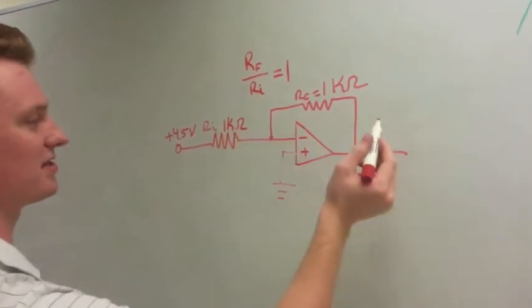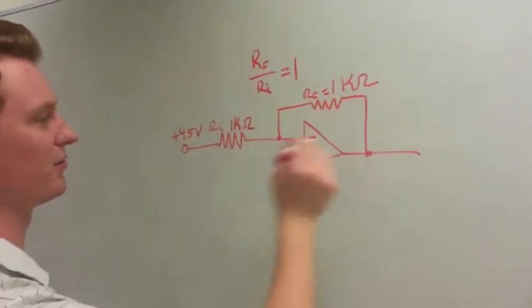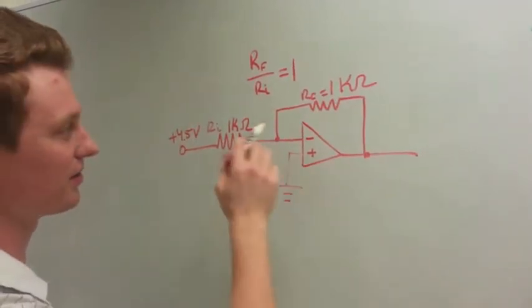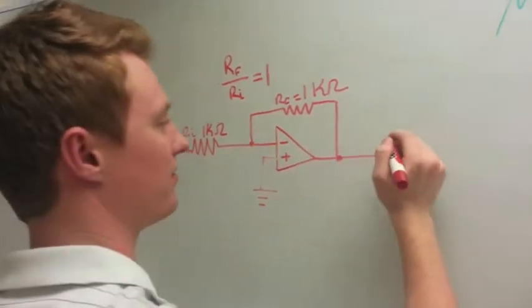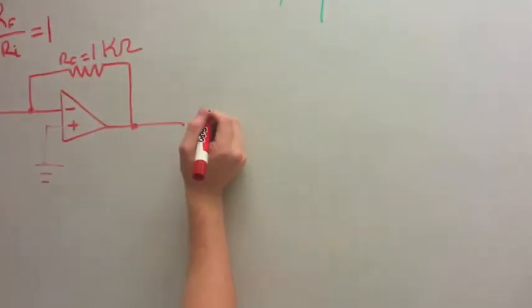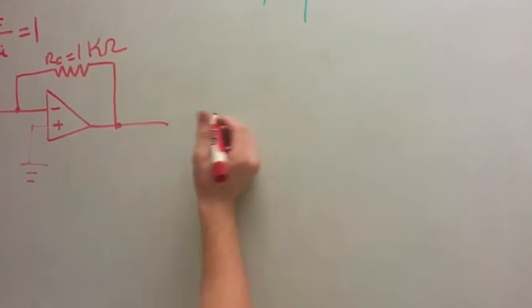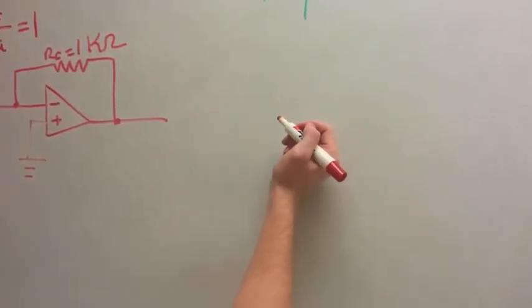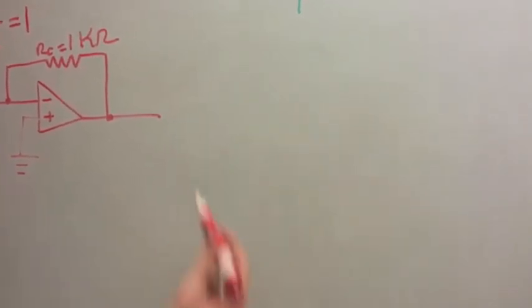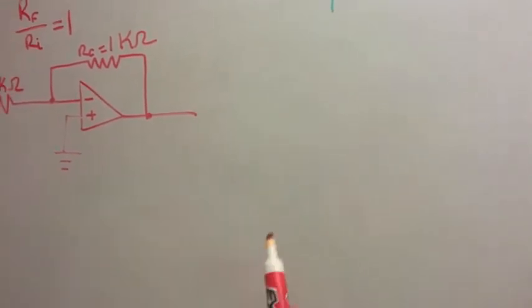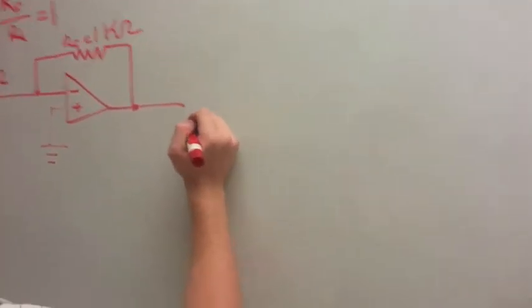Now this will get us a negative voltage input with a gain, or a negative current input with a gain of 1. So in order to fix that, we're going to have to use another inverting op amp with a gain factor of 10 because we want to be able to boost our audio by a factor of 10.